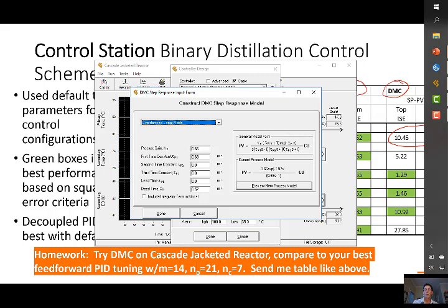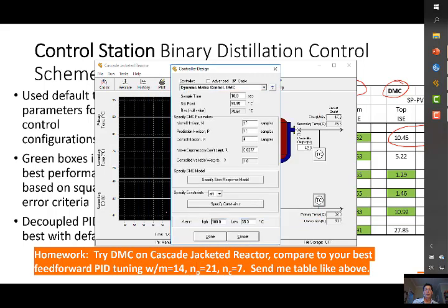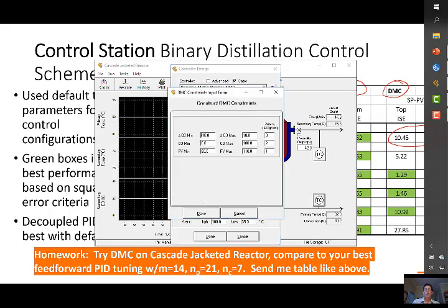The process variable for the primary is here, so that makes the current per the parameters given here. And you could play with that. In a DMC controller, one of the most important things to do is to specify the constraints. DMC is a constraint controller, and when you're implementing a DMC controller, this is one of the most important things that needs to be set right. I'm not going to mess with any of these right now, and DMC does have the capability of prioritizing the constraints. In this one, the movement of the process variable is given the highest priority.